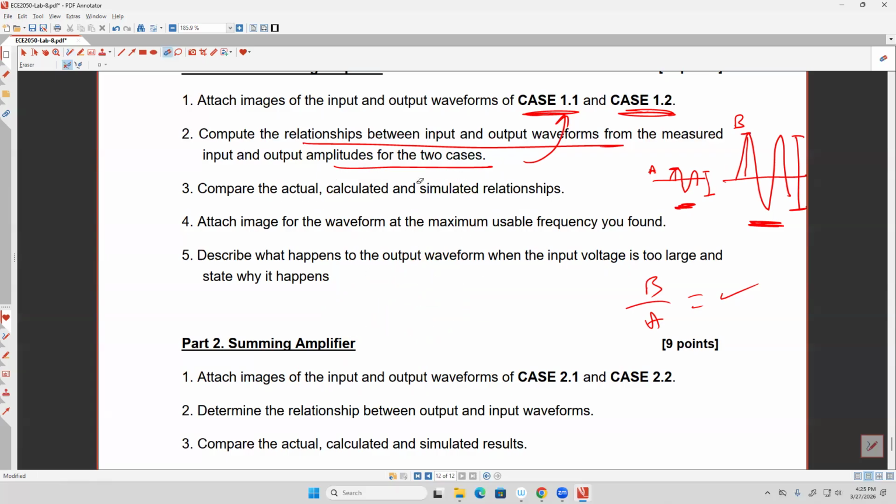But for sure, we're not expecting, if you are expecting a gain of 9, to get a gain of 3. No, this is wrong, right? But if you are expecting 9 and you get something like 8.8 or 8.9, something very close, yeah, this is something I can justify. I can say my calculations were based on ideal resistors. Resistors may be different, okay?